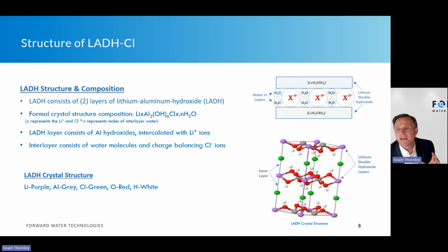So even though you have a lithium aluminum double hydroxide sorbent, it doesn't mean it's going to perform the same as someone else's sorbent, because of the differences in the formulations. That's why, within DLE testing and the evaluation and selection of sorbents, you have to do physical testing, because even slight changes in the formulations can impart significant performance changes within the media, some good, some not so good.